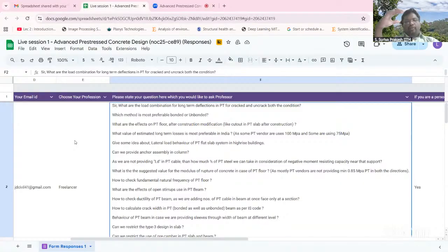But when you design the system for lateral load, wind loads and so on, we need to ensure that the gravity load system is connected very well with the lateral load resisting system, particularly the shear walls wherever you have placed them, or when you have a heavy moment resisting frame or braced frame system.